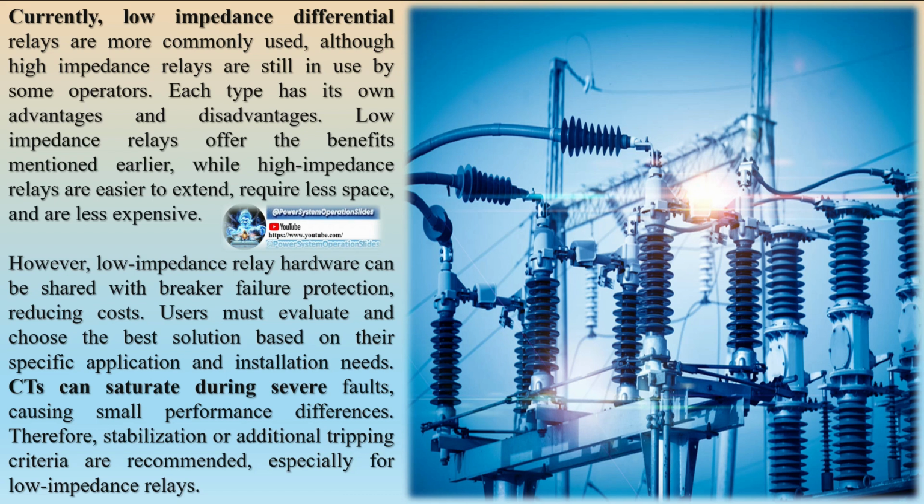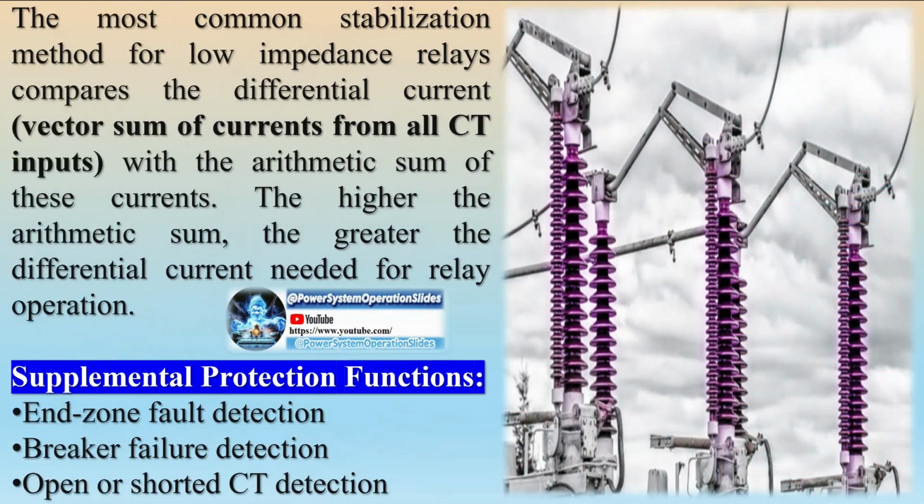Busbar protection systems protect substation busbars and associated equipment from the consequences of short circuits and earth faults. In the early days of power system development, no separate protection device was used for busbar protection. Remote end-line protection served as the main protection for busbar faults. As a result of increased network short-circuit capacity, dedicated differential relays for busbar protections have been applied to minimize the tripping time of the protection and to limit the damage caused by high fault currents. Today, busbar protection systems are used, and even double busbar protections may be applied.